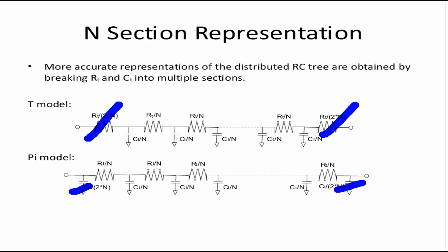But that value is the combined load. For example, the report timing report will show the combined value of capacitance at any pin. It will not show the section information, because it's just the way PrimeTime will reduce things. It will calculate delay. We can just read about it, but when we do static timing analysis, we should not be too concerned about it.